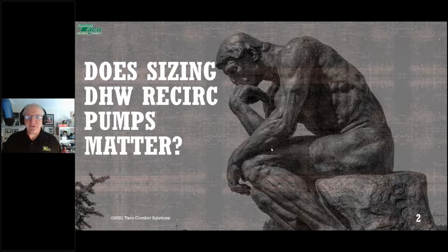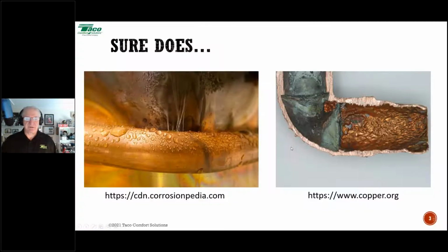Well, I will suggest to you that sizing does matter. When you sit down and ponder that, like Rodin's The Thinker, understand that yes, sizing really does matter, and it's the critical element of domestic hot water recirculation. Why does it matter? Here we see a couple of pictures of copper piping with pinhole leaks. If our sizing is too big, meaning we're pumping way more flow through the pipe than it wants, we're going to cause erosion from the inside out, leading to pinhole leaks.